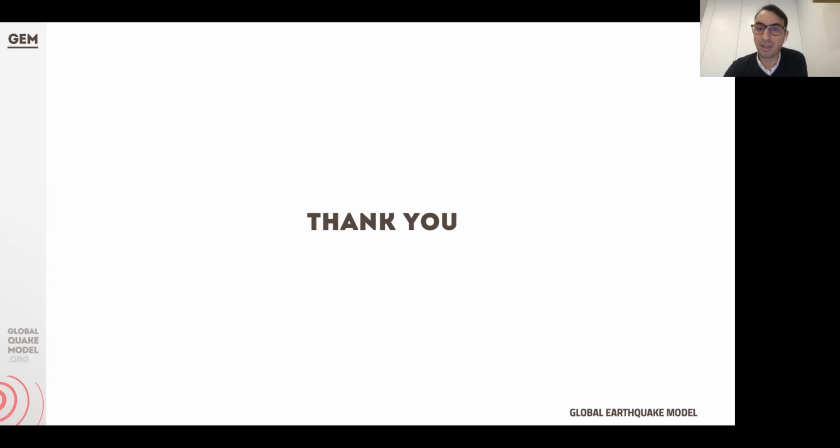So I think you have these two schools, right? You have the mathematical formulations, for example, the ones from the GMPs, where you know that each parameter, each component on the GMP has a physical meaning, right? And that's very nice. That's very beautiful. But I think you still see that for some combinations of magnitude and distance and Vs30, we still get values which are very strange, sometimes very high, sometimes very low. And I think this is a lot of times because we are extrapolating these mathematical formulations to combinations of parameters that we didn't have the data for.